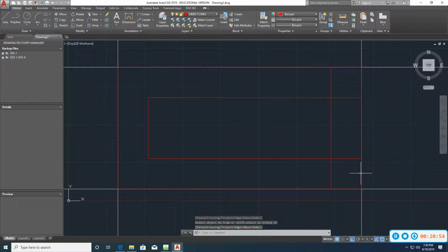And you can tell that there's a notch cut out from the side. So this line right here, I'm going to offset it 5 upward. Offset 5 because it says it's 15. From here on up is 15. Okay, enter. So I'm going to trim this up now.